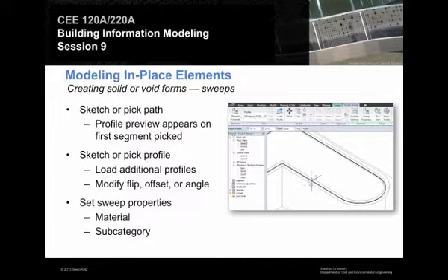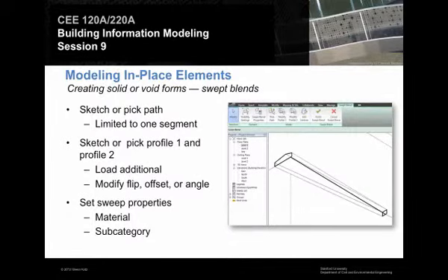The last variation on this theme is the swept blend. What does that do? Well, it merges the two. If they got together and had a kid, they would have a swept blend, where it's two different profiles that are morphed along the path. You don't use that all that often, but there are occasionally times when you want to use it. So those are your big five: extrusions, revolving, sweeping, blending, and swept blend. Using those five basic techniques, you can create anything, basically.